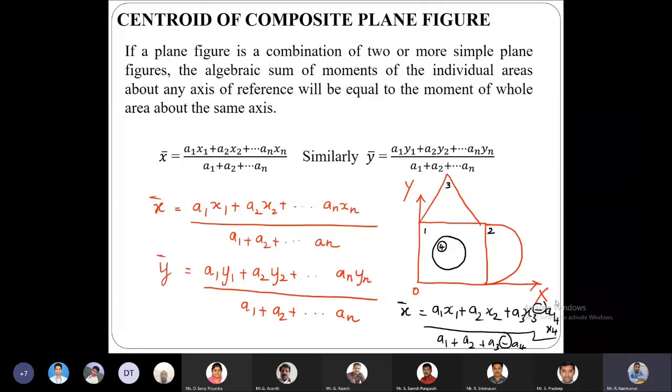We have to be very careful here, because we have to tell the students that this is only a general syntax. This general syntax works only when we have material present in the given figure. If we have a cavity, we have to use the appropriate minus sign for the corresponding shape, with the appropriate number for that section alone. So let us see some basic problems and then we will go to the centers of gravity.